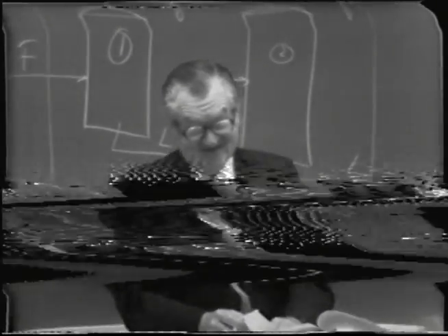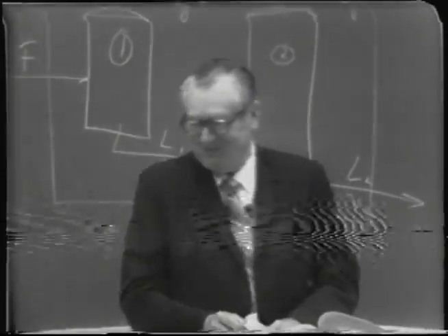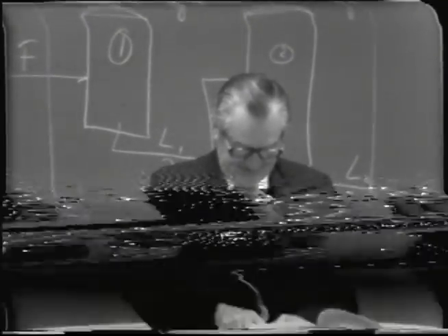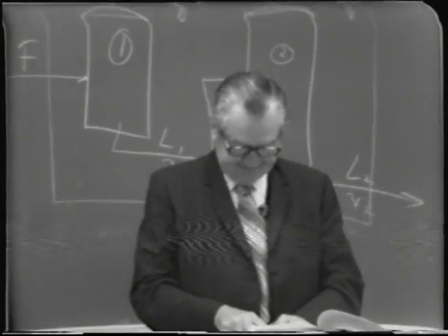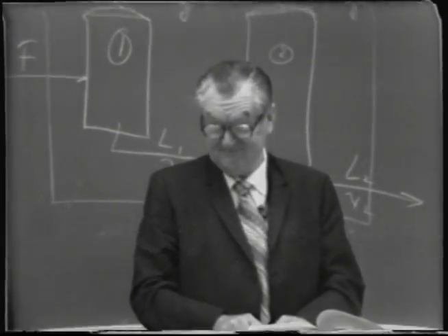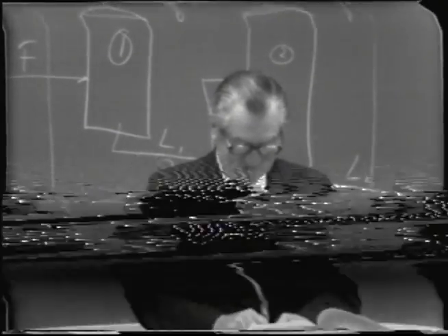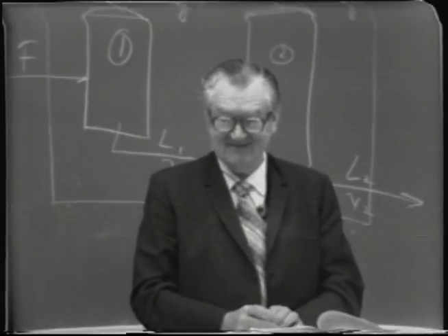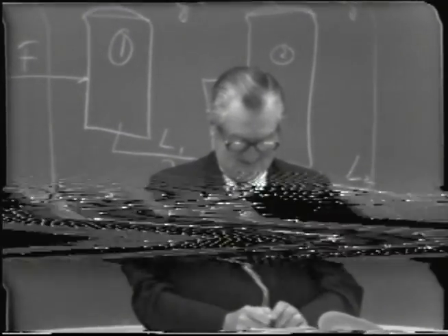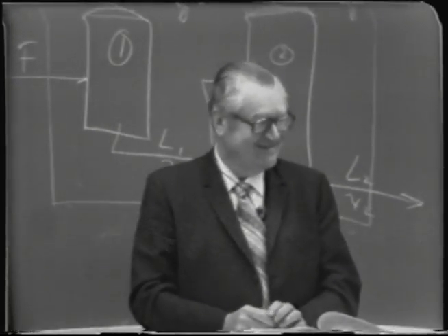Well, I'd answer that as a misinterpretation of the problem then, because it does say, as I read it here, the percentage of the more volatile components recovered in the combined vapor streams from both stages. It doesn't say anything about total overall recovery. It says how much of that volatile component is in that vapor stream. How much is recovered in the vapor?